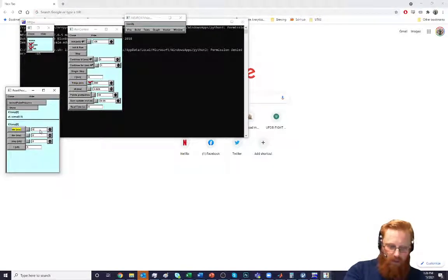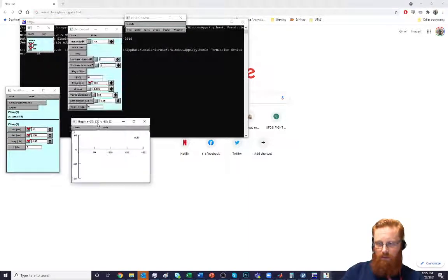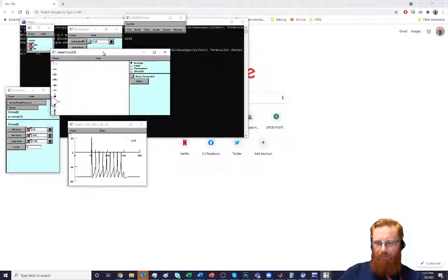So then we can have 50 milliseconds of delay, 100 milliseconds long, and like 0.05 if memory serves. Let's just check that works. Right, so we're going to go graph, voltage axis, and run. Wonderful. Good. Okay, so now let's get into the sort of difficult bit. So we're going to go build linear circuit.